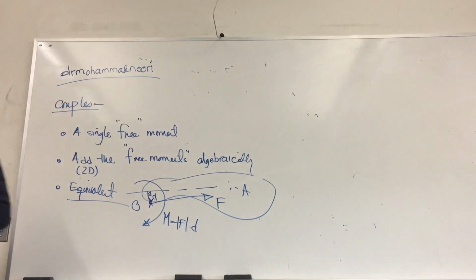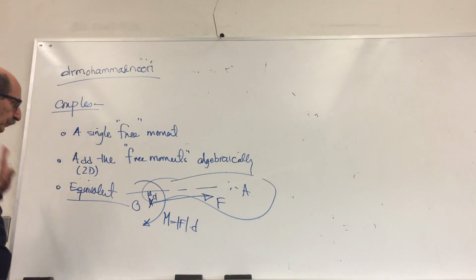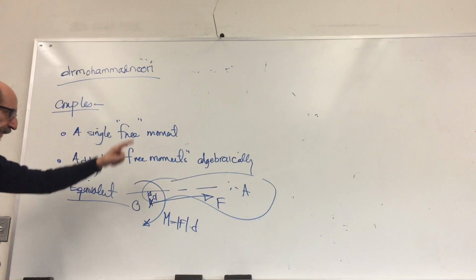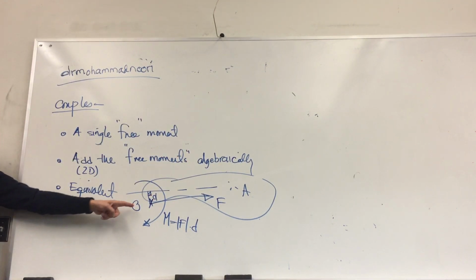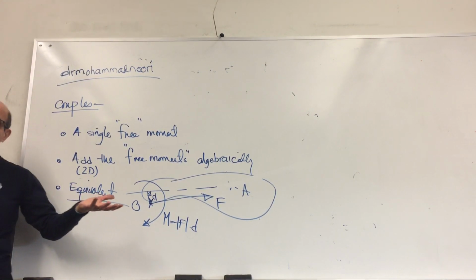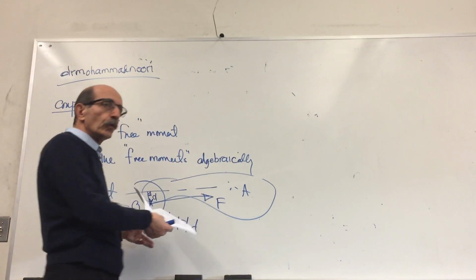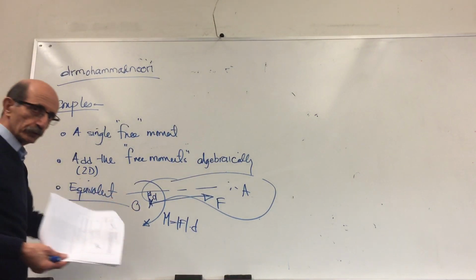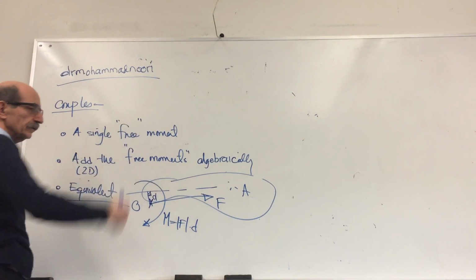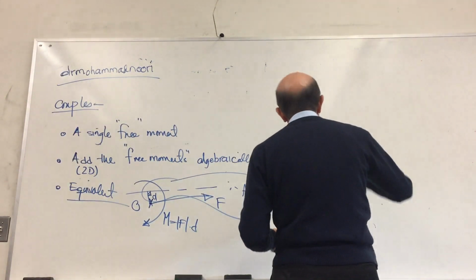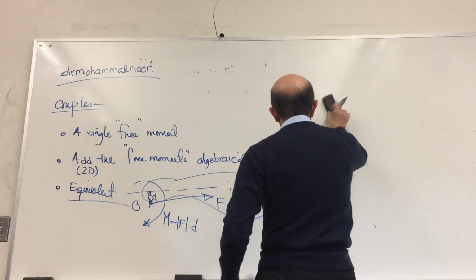Or in other words, you can move a force from wherever it is acting to any other location by simply moving that force, same orientation, to the new location, and add the moment of that force about that point at that point. That's the definition of equivalent system. So you have several forces, you can move all of them to a single point by just adding the moment that those forces create about that point and putting the resultant of those forces at that point. So that's what you want to do. Do an example that would be just that.